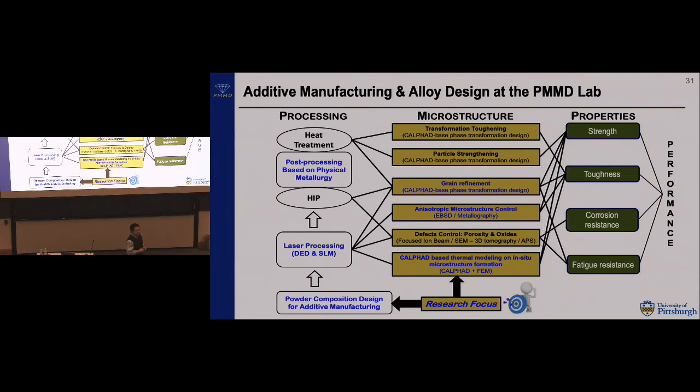utilize this for additive manufacturing. So additive manufacturing is a kind of technique. I probably don't want to show a lot of movies, but you can easily check with YouTube, right? So it's actually a layer-by-layer printing deposition process. And you can spray one layer of powder and select the geometry that you want to melt for one layer. And then after you finish, spray another layer, and then you melt, okay?